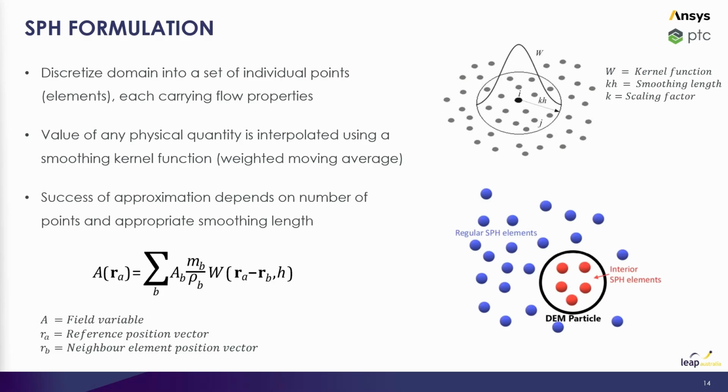Instead, the coupling of these two models is executed through basically a solid fluid no-slip boundary condition. So importantly, the method requires that the solid particles are sufficiently larger than the SPH elements or the mean interparticle spacing for the SPH elements.